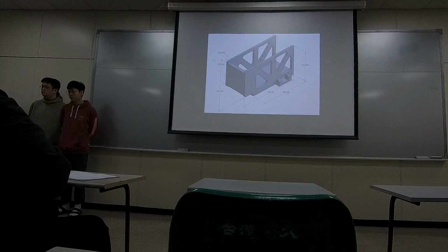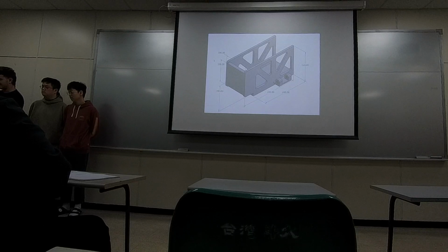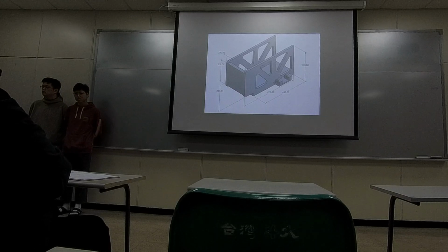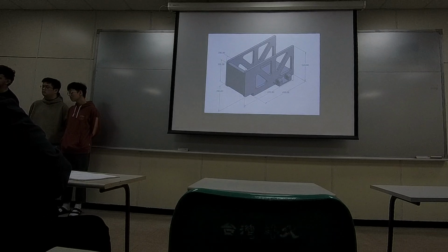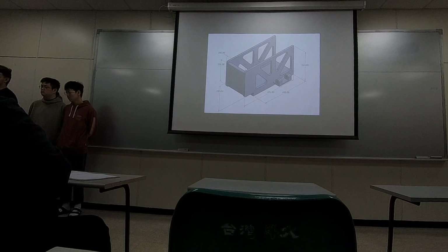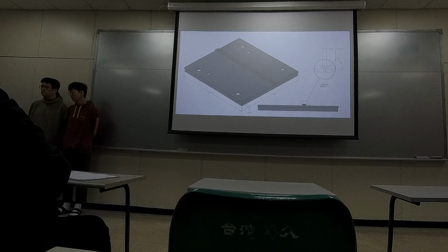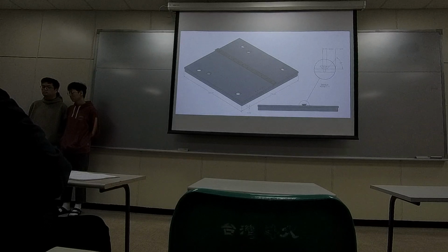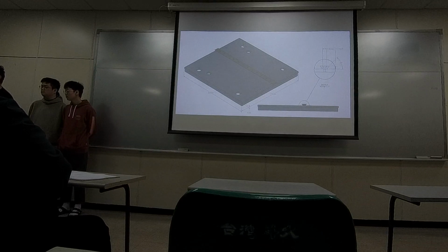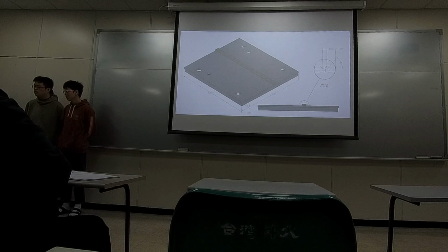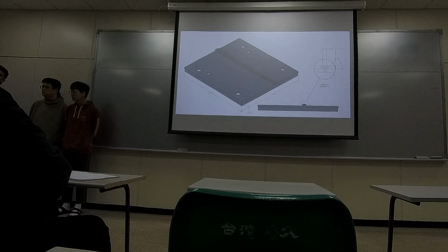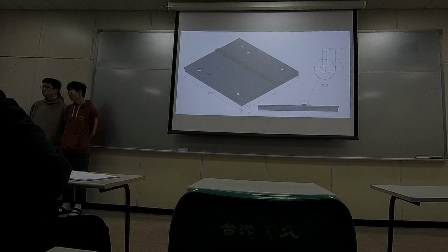Okay, so this is the moving part with these dimensions. Nothing spectacular, I believe. Here we have a very big plate on which the gripper is mounted. I think it's around 35 millimeters in thickness. And we have these side walls with triangular holes for weight reduction in it, and then a nut for the worm gear. This is the base plate with a dovetail. The base plate hasn't changed at all compared to the previous generation, we just redesigned it for our purposes. So these are new holes in it, and also the dovetail mounted. It's pretty thick, so I think it can withstand the weight of the moving part with 50 kg rolls mounted on it. We'll show that later.